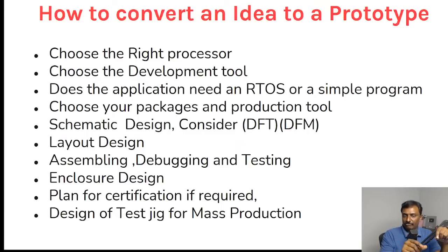Design for manufacturing means you should be able to manufacture this board easily. The connectors should be suitable. There are considerations for design for testing and design for manufacturing; that itself is a separate topic. Then layout design. Finally, assembling, debugging and testing, enclosure design, and planning for certification if you want, like CE certification or FCC certification. If you want to sell your products in the US market, then you need FCC certification.